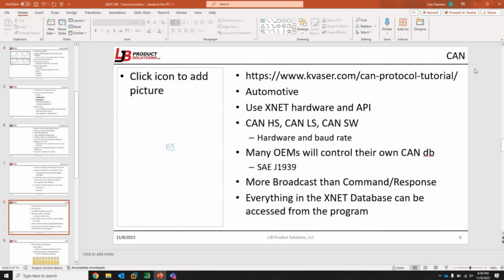So at Stratic, we used Thomson linear actuators. They're Electrak HDs, I believe was the part number or the model name, but they ran on CAN. So we could just send messages over that I want number 8 to extend to this position, and number 8 would extend to that position and feed back over a message, here I am, I'm at this position. But yeah, I'm pretty sure Thomson did design those to be used in our testing application. They were designed to go on tractors and lift large things and move large things.